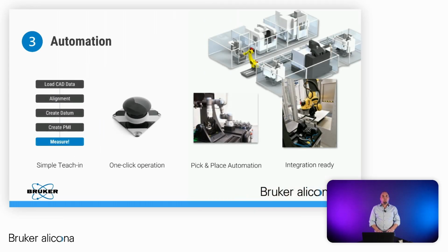At the left side, you see for our vertical solution, according to the precision dies, the workflow. You have to load the CAD data, you have to align it, you have to create the datum, you have to create a smart PMI, and then you have to click on measure. If these measurement tasks reoccur, you have a one-button solution already. But we are going one step further.